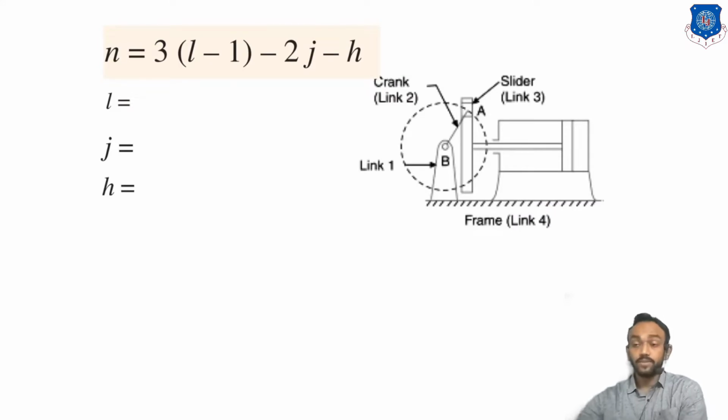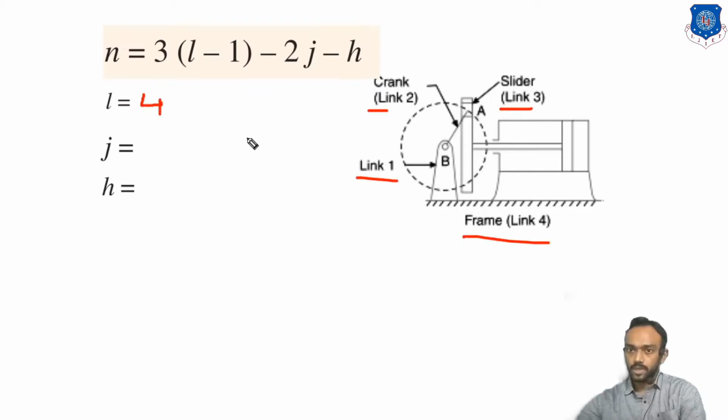So these are some inversions of the double slider, and they are asked for degree of freedom. And always remember that in all our inversions, the 11 inversions we have studied, the degree of freedom is 1. Okay, remember that, it will be useful. So check this, the number of links is already given here, 1, 2, 3, 4. How many joints are there? So check this, this 1 is fixed and 2 is a crank, so there is a turning pair. You can check here, this is the turning pair 2, and this slider inside this.